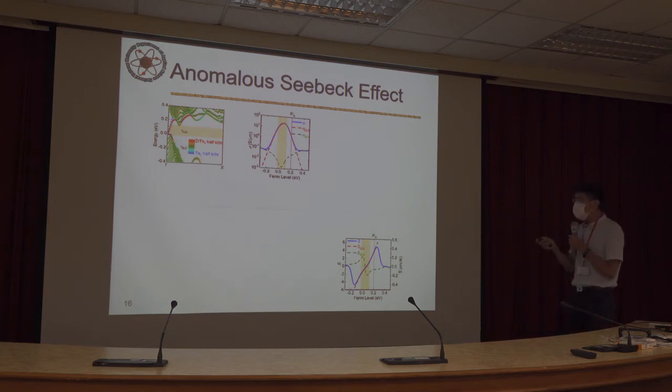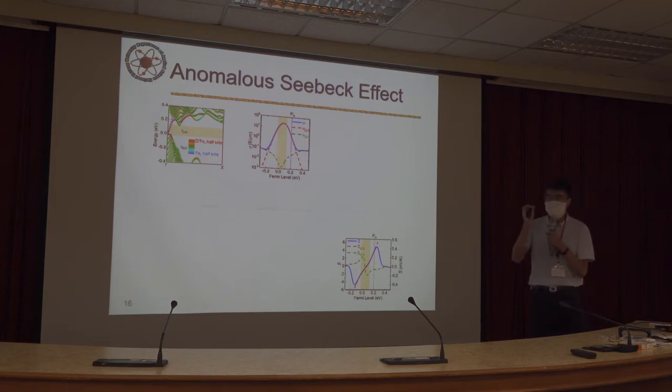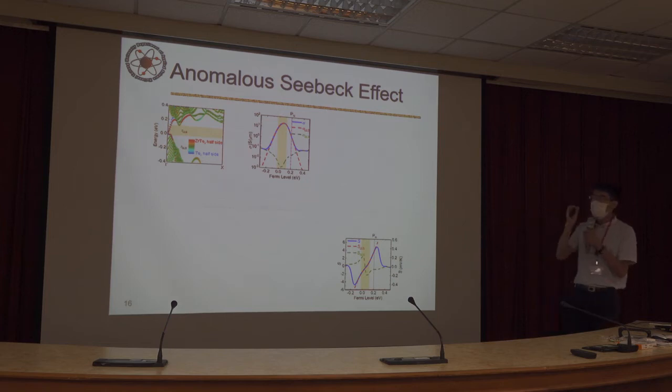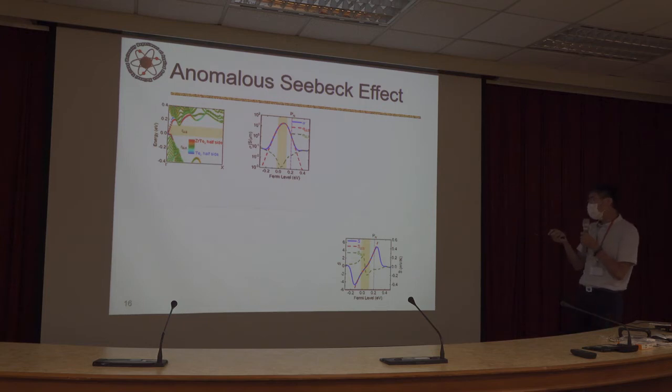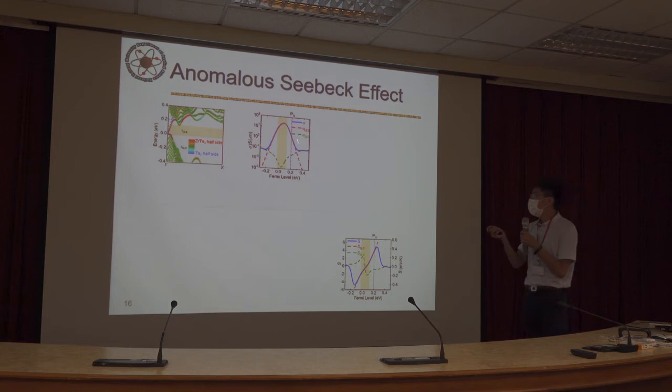So let's first see the electrical conductivity and the Seebeck coefficient as functions of Fermi level. We first see the green dashed lines. The green dashed lines are those only considering the short lifetime state, so they show the behavior of normal semiconductors. While the blue dashed lines are those incorporating the in-gap long lifetime edge state, so they show the behavior of topological-insulator nanostructures. Here we can see the topological-insulator nanostructure indeed shows behavior qualitatively different from normal semiconductors. Besides, you can see at the optimum Fermi level, even though this is in the short lifetime state energy region, the electrical conductivity is quite high and dominated by the long lifetime state.